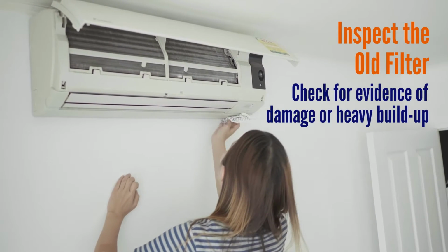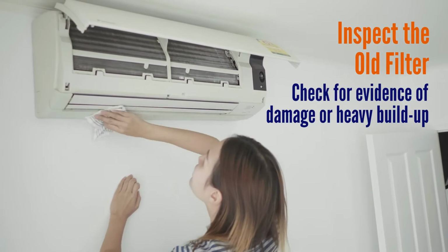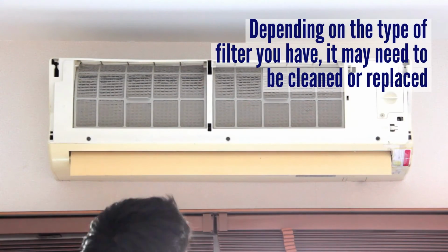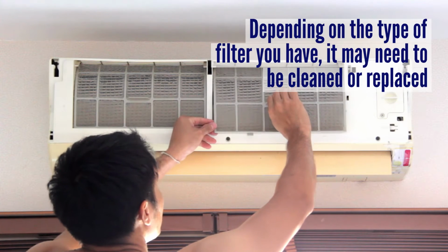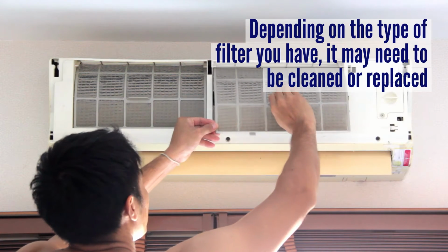Next, take a minute to inspect the old filter for evidence of damage or heavy buildup. Depending on the type of filter you have, it may need to be cleaned or replaced. Keep in mind, many factors contribute to how quickly a filter can become clogged.